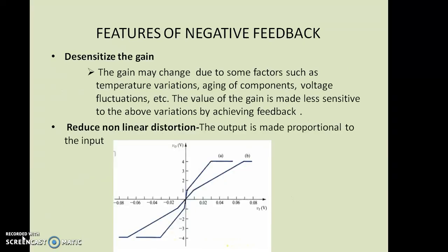There are some features of negative feedback. One is that it desensitizes the gain. That is, the gain may change due to external factors like temperature variations, aging of components, voltage fluctuation, etc. The value of the gain is made less sensitive to the above variations by feedback.